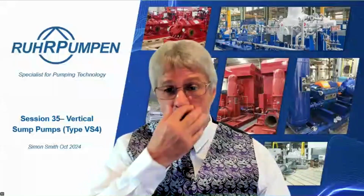Daniel Gervais says, could you detail why double row bearings are required when a 2-pole speed motor? Is it related to the upthrust? No, it's not upthrust. It's just the amount of thrust generally. If a pump is running at 2-pole speed, it develops higher heads. And if it's developing higher heads, there will be higher thrust. So you need a double row bearing instead of a single row bearing. If it's running at 4 or 6-pole, the thrusts are very, very much lower.